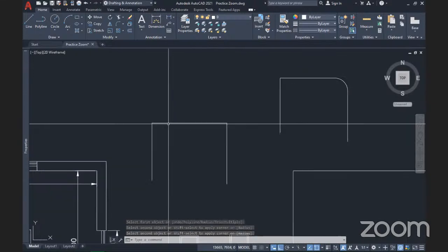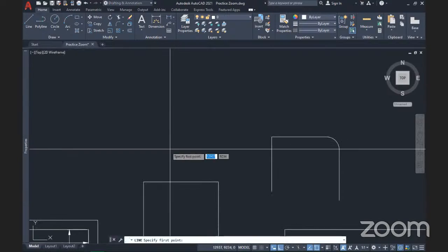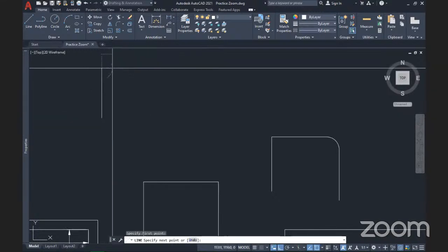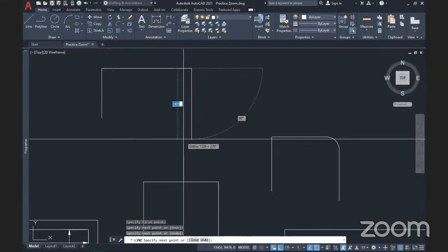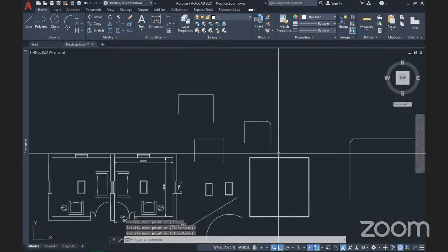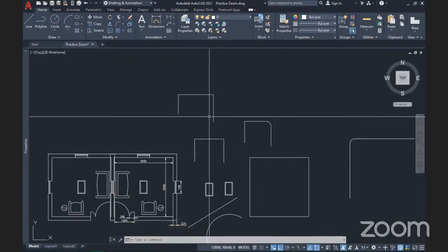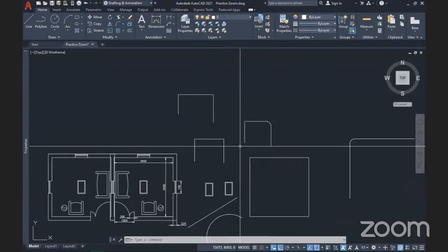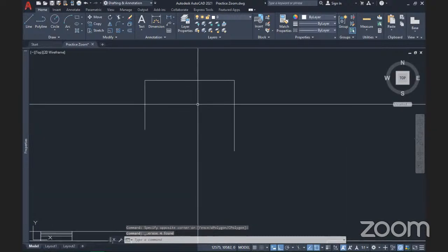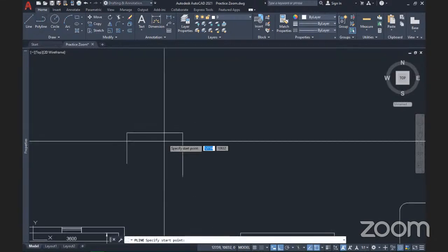For explanation, I did something. I drew two lines explaining the difference between a line and a polyline, and I talked about the connection of those lines. Like this one is being created using the line tool. I have to delete this one so we have space. These objects right here, this shape, is created using the line tool. While the next shape I'm going to create, I will use the polyline, like so.